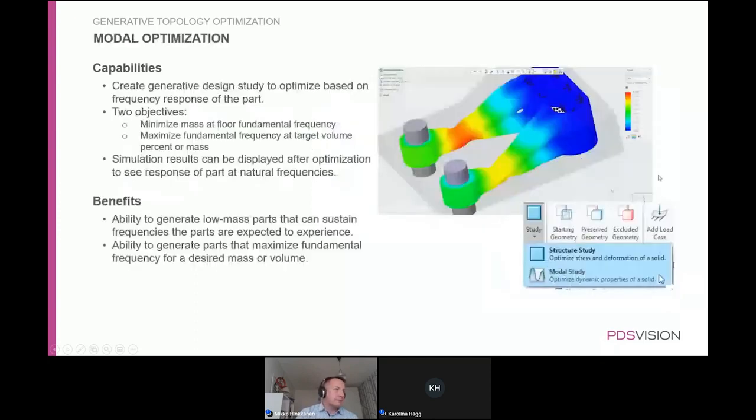What else is there? Previously we had structural analysis only. Now there's a modal analysis as well. For some applications vibration is important. Even if you have a nice geometry which will hold the loads, if it starts to vibrate, it's basically useless. So today we can also set a first or second modal frequency or mode shape as limitations, so that vibration studies are also considered while designing these geometries.